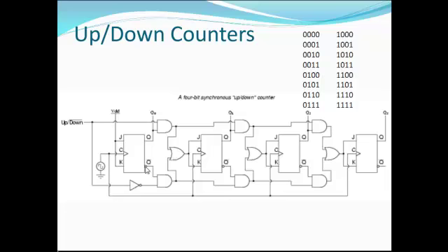However, this Q0 outputs a 1, and since this input is 0, inverted into a 1, 1 ANDed with 1 is 1. ORed with 0 from here outputs a 1 into this JK flip-flop for the next clock signal. This, of course, inverts this Q1 into 0, and this process repeats, causing the circuit to continuously count down while this input remains 0.